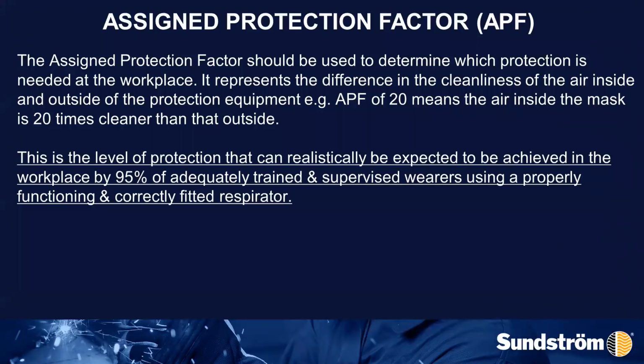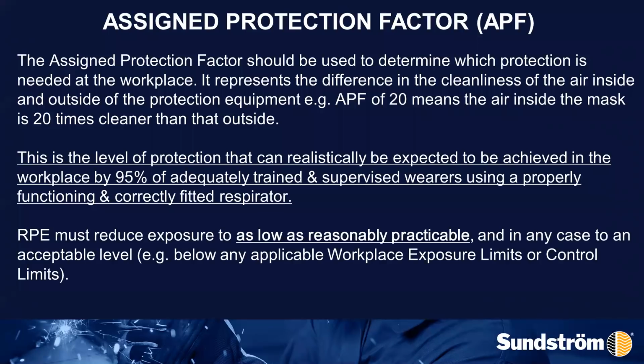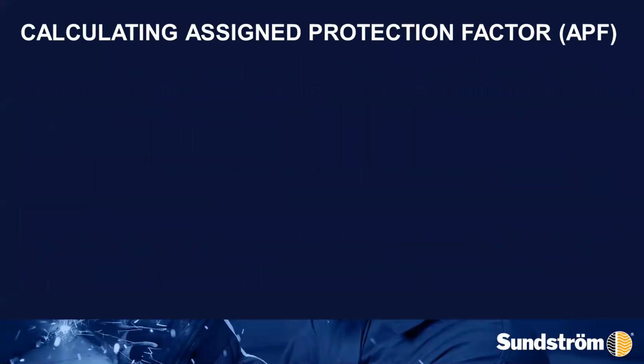So just giving someone a mask is not good enough. They need to be shown how to use it. You need to make sure that it fits them for it to get that sort of level of protection that it's designed to do. And of course, in all instances, we need to make sure that it reduces the exposure as low as is reasonably practicable, and of course, below our old friend, the workplace exposure limit.